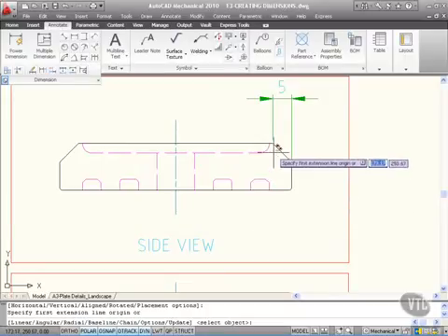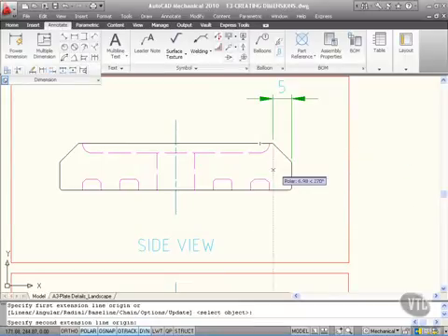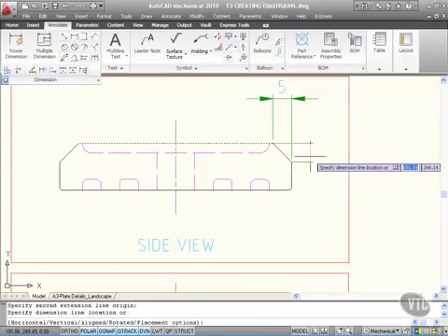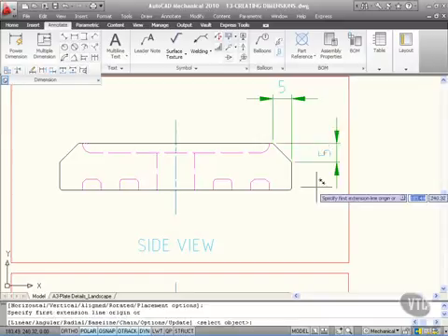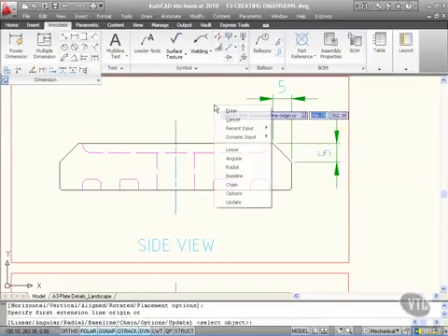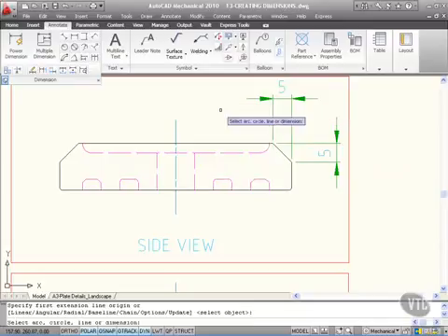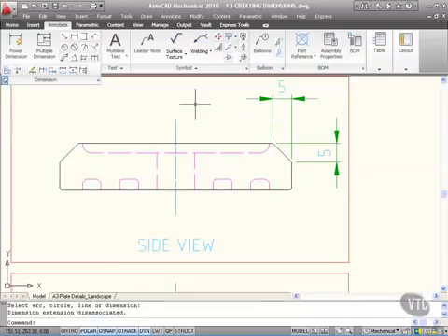Next extension line origin, that'll be a node there now, and a node there now because I've already placed a dimension. But I'll come out there, click, and there's another dimension there like so. I right click now and enter. And now it's asking me, do I want to do an arc, circle, line, or dimension? So do I want to edit anything in particular? Well, I don't in this particular case, so it's just an enter to finish. So there's my power dimensioning.